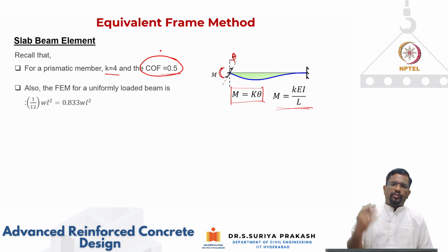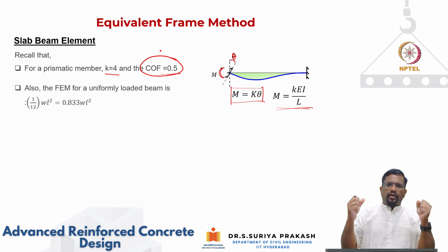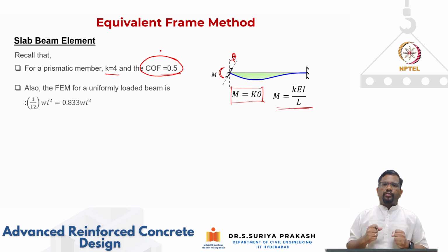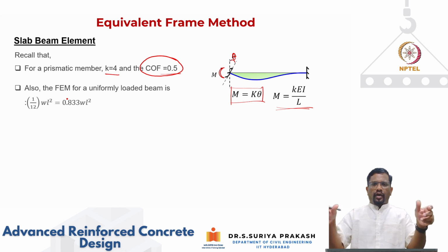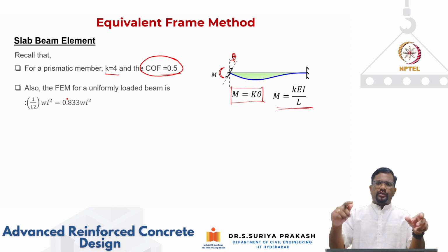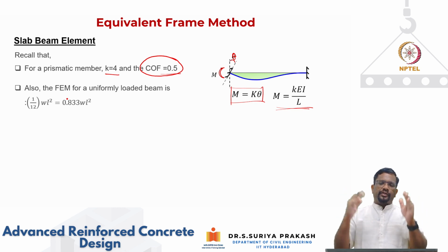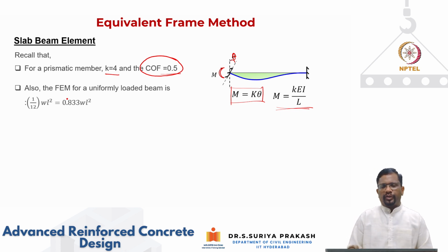Okay. And if you remember your displacement method of analysis, how do we do it? First, we lock the two joints, because I'm blocking these two joints from rotation. When load is applied, I'm going to develop some negative moments at the two supports, which is equal to WL square by 12. Then what we do? Slowly we unlock and lock the joints in a successive manner until the joints have achieved their final positions of rotation. That's what we do in the moment distribution method.